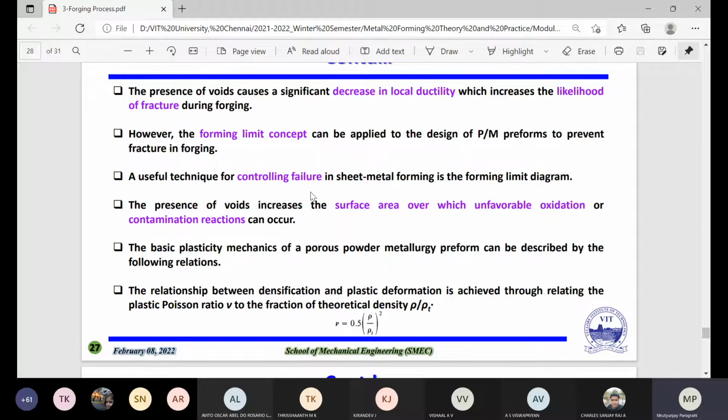So all the parameters you have to think about, because sometimes we do heat treatment in vacuum. Okay, so some people tell me, sir, if we make a vacuum, it will be good. But the moment you make a vacuum, the waste gas or volatile impurities inside will go out. But how will it go out? There is no space to go out. So it will accumulate, and then high pressure will build up inside, and something more can happen. So you have to provide some inlet there.